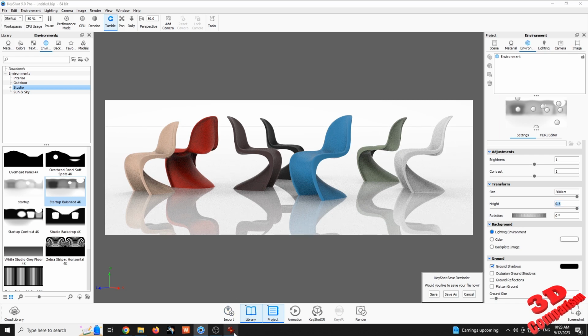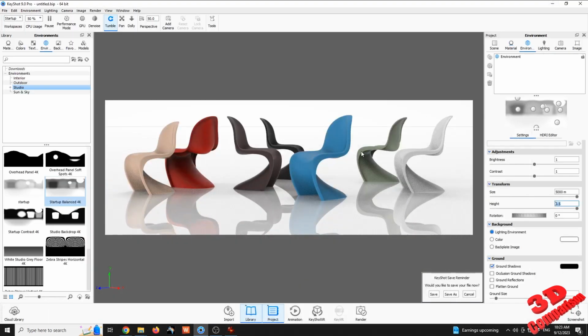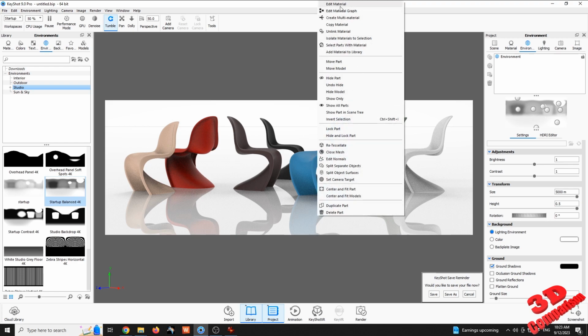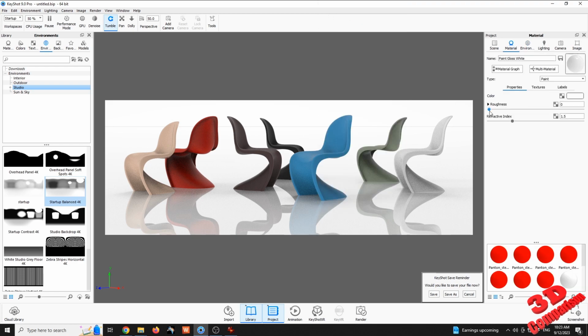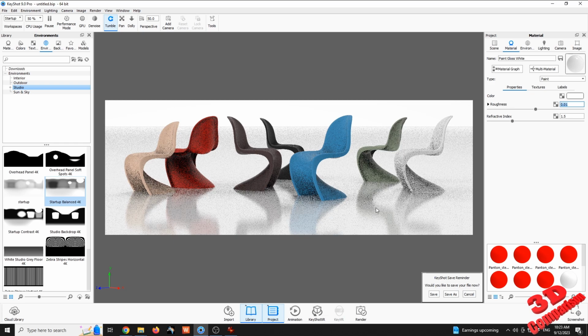And what we also need to change is to make these reflections a little bit softer. So I'm gonna select the material for the ground plane, and I'm gonna slightly increase the roughness. Let's see, 0.05 will make it like this. So this is too much. With 0.01, we're gonna have some slight elements over there within the reflection. We can even go something more, 0.03 for example.